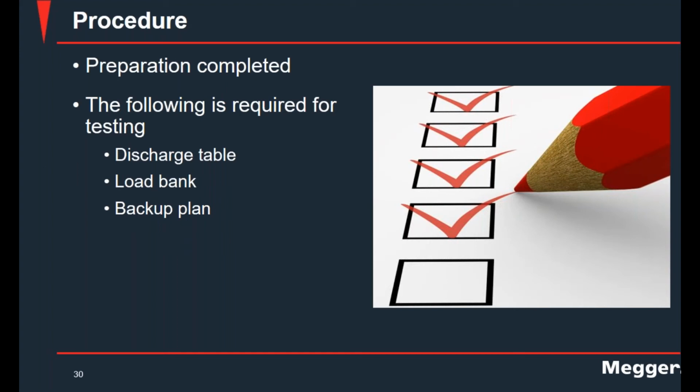Then you need those discharge tables. You need a load bank, you need means to discharge the battery, and you also need a backup plan in regards to the batteries that you're going to use for supply, and what if something happens. And I'm discussing those things now.